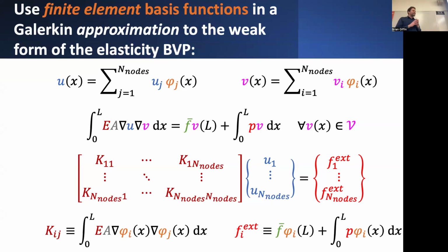But now you'll probably see a little bit of a problem here. Notably, these expressions that I've constructed for the individual entries of this matrix, which again is nothing more than the stiffness matrix, the thing that we described as being this relationship that establishes how individual forces that show up at the nodes of this particular structure are related to incremental changes in the displacements at those nodes. That's basically what the stiffness matrix tells us.